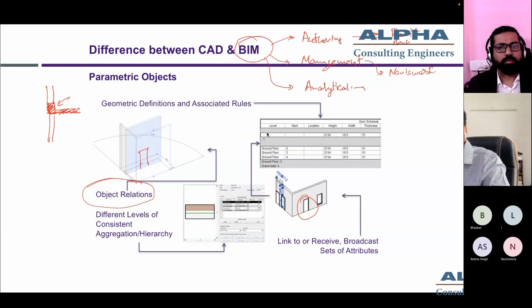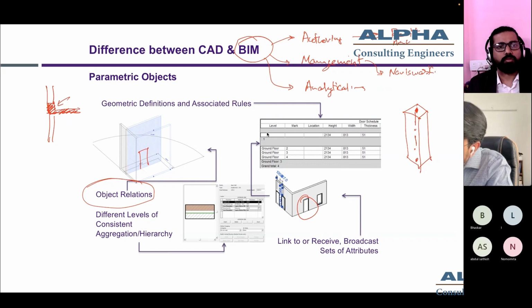So nowadays, BIM tools are having the analytical model embedded inside the individual elements. So let's say if a structural column is being created in Revit, there are associated analytical lines inside this column. If I am having a slab created, there is an associated analytical plane with it.